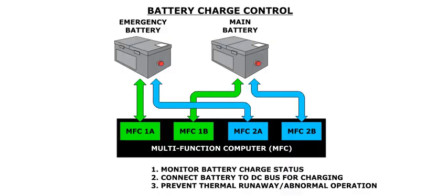The multifunction computer, or MFC, monitors the status of the batteries. If either battery requires charging, the MFC will connect the affected battery to the associated DC bus to allow it to charge. In addition, the MFC will monitor the charge current and the associated DC bus voltage to prevent a battery thermal runaway condition, or an abnormal battery operating condition.